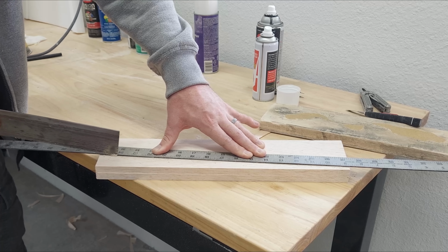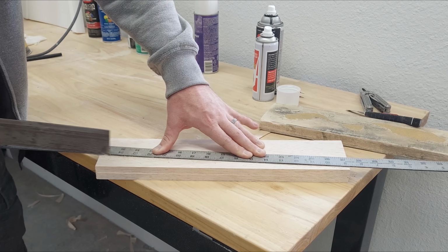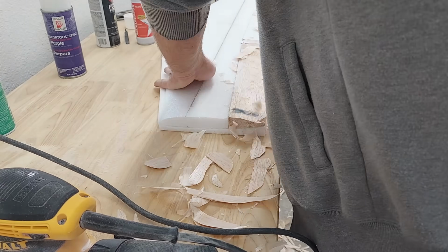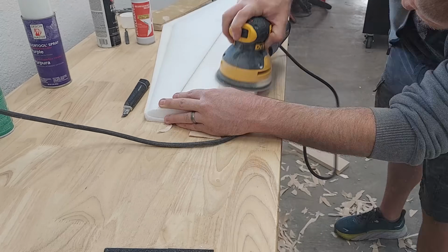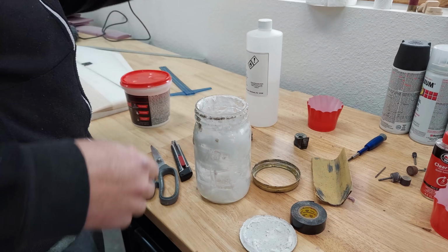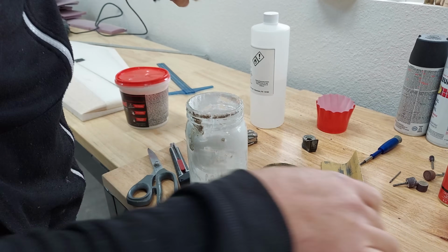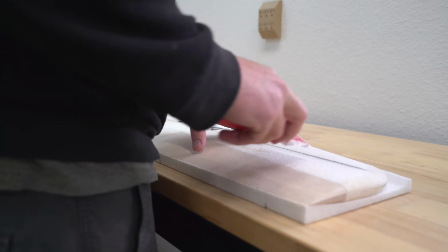The elevons are solid balsa and attached with kicker and medium CA glue to the cores. They are then tediously cut back to match the original foil as best as possible. Definitely not molded airframe quality here. A mixture of lightweight spackle, goop, and propyl acetate is used to prepare the wing cores for covering. Each layer is allowed to cure and then sanded back.